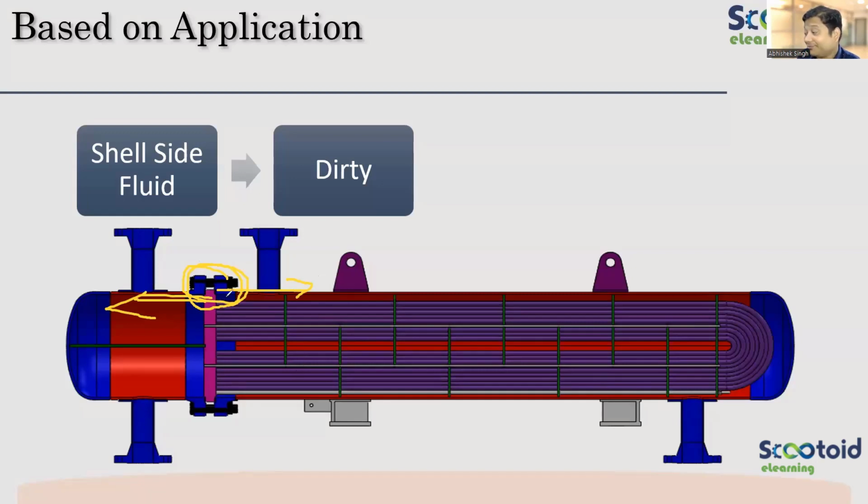Okay, so the tube sheet, very right, Kiran. Tube sheet is not welded. Remember that. It's sandwiched between two flanges. Now you know why this configuration was there, where both sides there is a flange. I could have extended this tube sheet and welded it with the shell. If I do that, can I remove the tube bundle for cleaning? No.